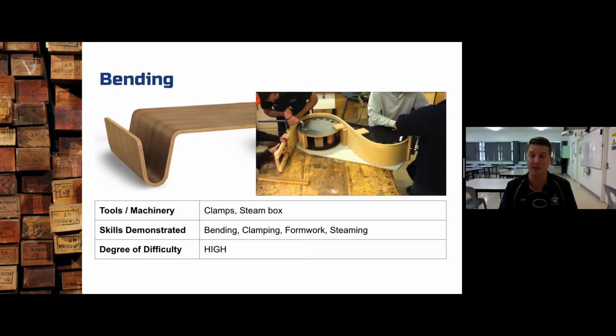To make sure that our timber stays stable, we season it so that it has approximately the same amount of moisture in it as the air around it, so that the timber stays fairly stable, straight, no kinks, no bends, no warping, no other defects caused by moisture.